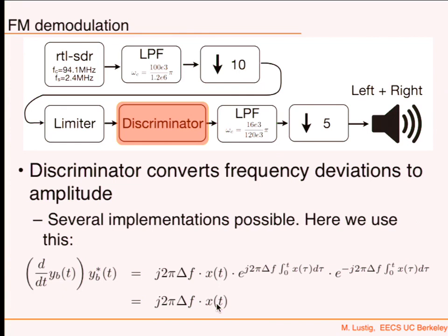How do you take a derivative? That could be a question. Finite difference could work. If you look at the DTFT of a finite difference, it looks like a derivative in the low frequencies, but it rolls off in the high frequencies. So the Fourier transform of a derivative is basically a linear function in the frequency domain, while finite differences actually roll off.